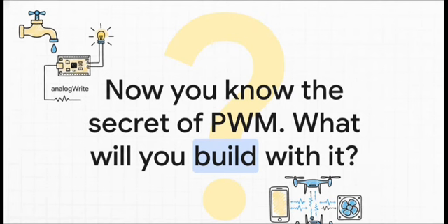So, what's the big takeaway from all this? Pulse width modulation is the elegant digital answer to the messy, inefficient analog problem of controlling power. It's a simple idea at its core: use time to fake voltage. We've gone all the way from a water tap to sinusoidal modulation and harmonic control. But honestly, the best way to really get this is to try it. If you have an Arduino or something similar, just hook up an LED and a resistor. Play with that analog write command. See the light change. And as you do, you'll know that you are now controlling the very same